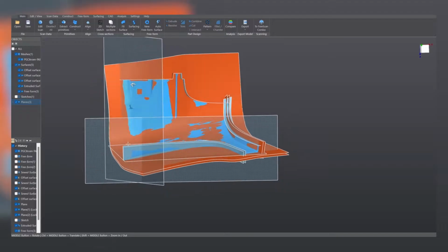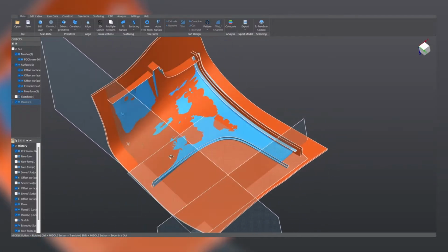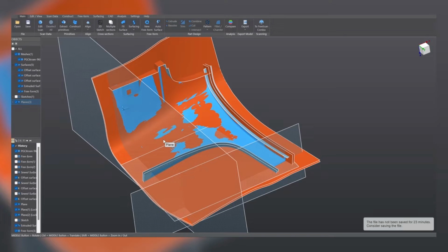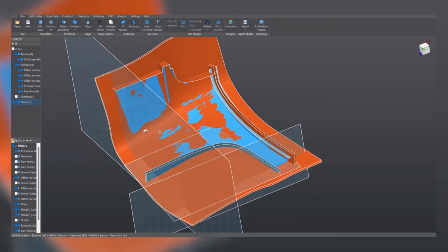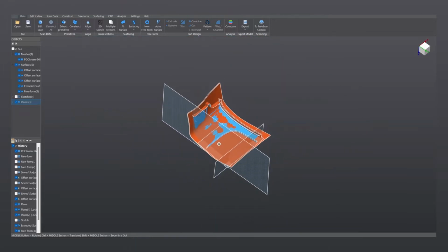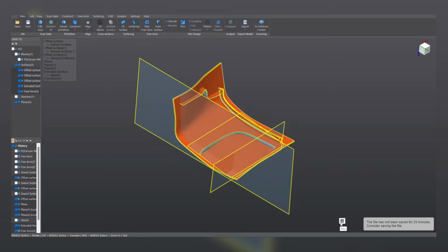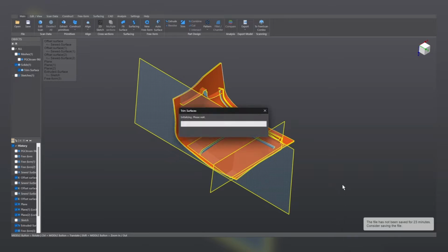And now we have all the surfaces and planes, all the features, to close a solid, and so obtain the shell of the mesh, which is going to result in a solid body. In order to obtain that, let's hide the mesh. Let's select all the surfaces. And we are going to click on this small button over here, which is trim. Now the software will need some time to compute all the intersections between all the surfaces, and we are going to continue later.